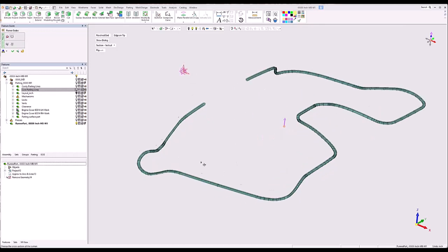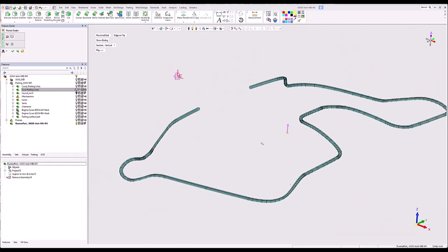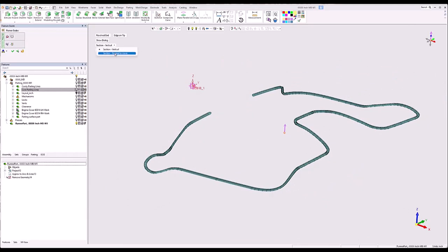Okay, so I get a result, but you can see here that's not exactly what I want. Let's change this to normal to curve. Now the failure originally, sometimes the geometry of that curve, there's something about it. By going into wireframe approximate to arcs and lines, it simplifies or cleans up that curve. And now going into the runner command, I get a result that's a lot better, a lot cleaner than previously.